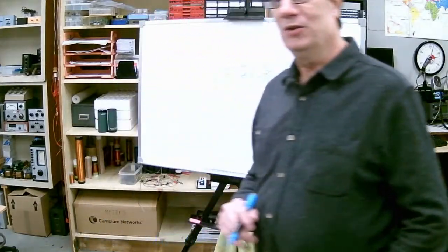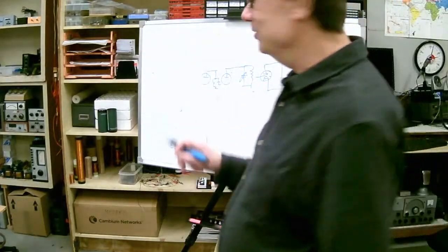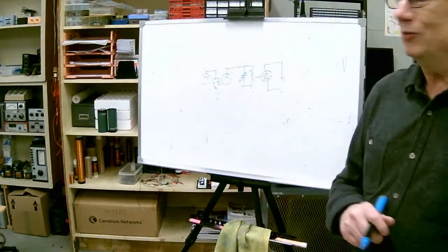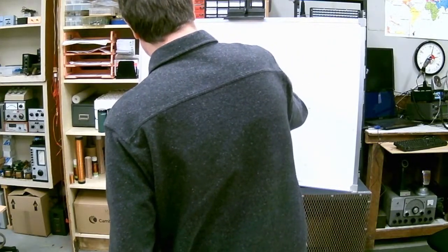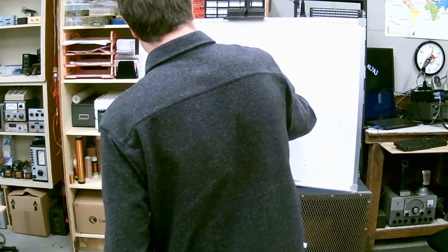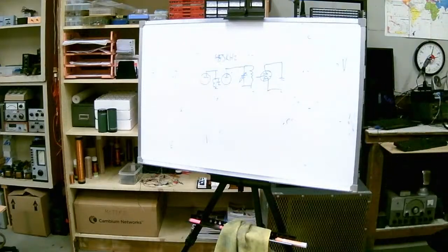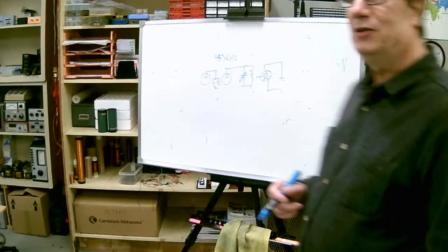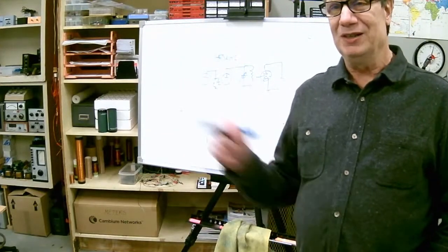Well, that doesn't do you any good if you want to listen to multiple stations. Well, this was not tuned at the frequency you were listening to. It was tuned at some intermediate frequency. So we installed what was, very early in the game, standardized at 455 kilohertz, which is outside the actual broadcast band itself, which is a good thing. You didn't want that happening inside the frequency. So all we had left to do was convert the incoming frequency into that.